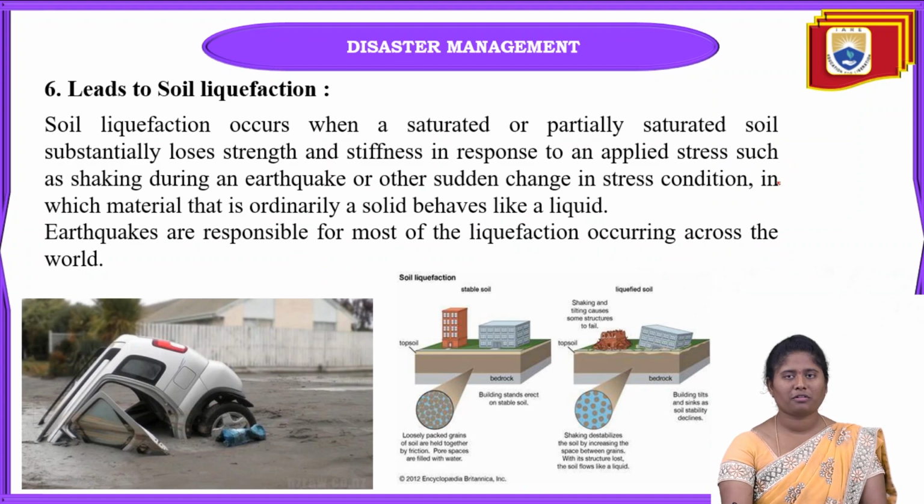And coming to the next one, due to earthquakes, soil liquefaction is going to occur. What is meant by soil liquefaction is that saturated or partially saturated soil automatically and subsequently loses its strength and stiffness in response to an applied stress.